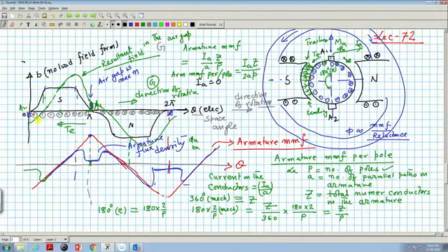Welcome to the 73rd lecture on Electrical Machines 1. In our last class, I told you how to get the resultant MMF distribution or B distribution in the machine, and the conclusion was that in the trailing pole tip flux density will be concentrated, which we understood from our qualitative way of discussing things.